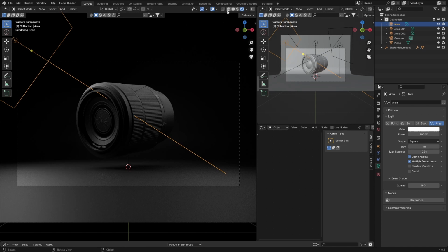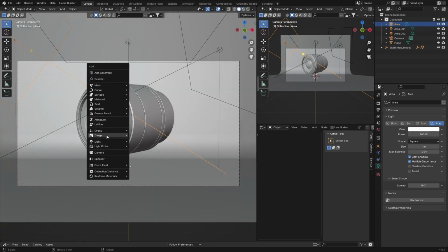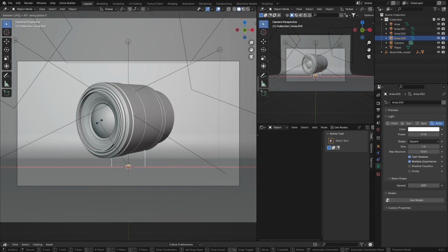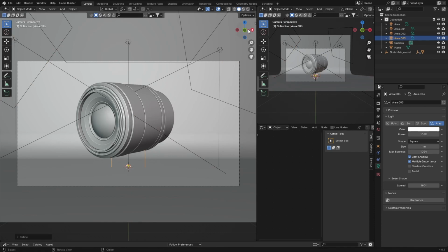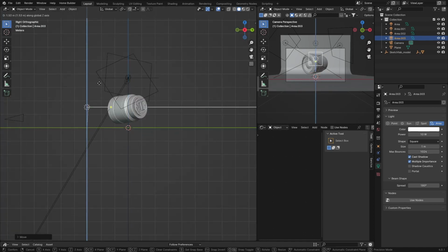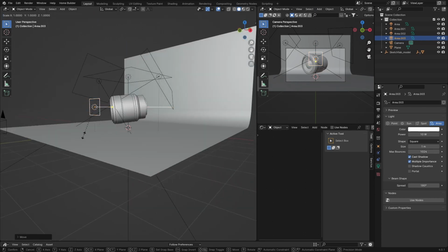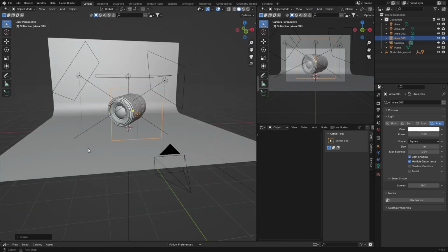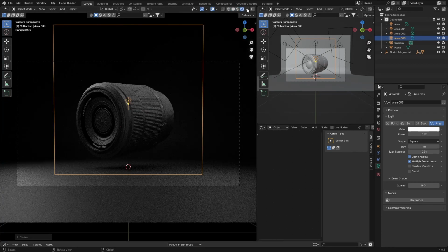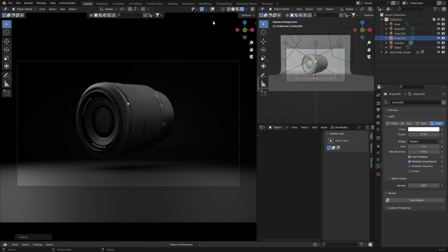And then last thing, if you want, you can light it with one more light. So let's go back here, Shift A, light, area, and go RX 90, and then just go here, go G, bring it back, G, bring it up, and then S, scale it up to there. Now let's go back to camera, go back to Cycles, hide this, and you can change this to about 25. That brings this up as well.